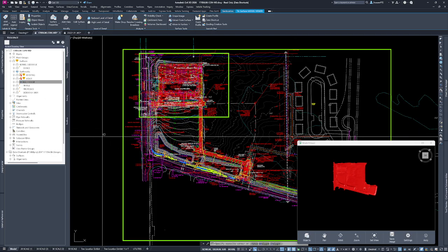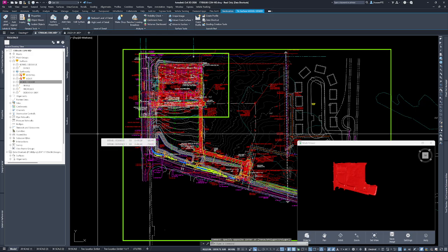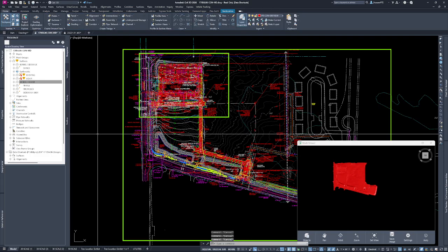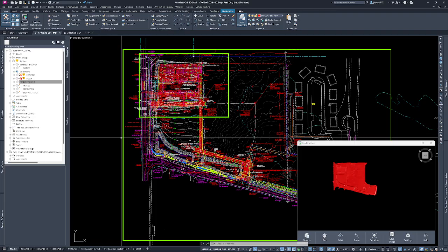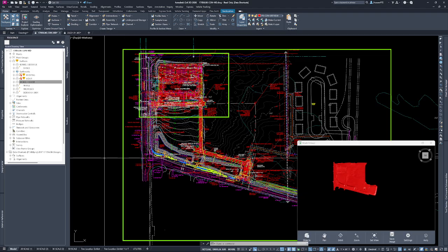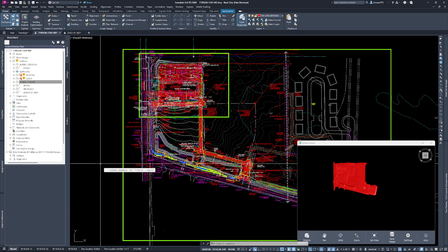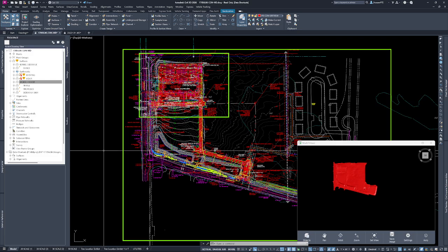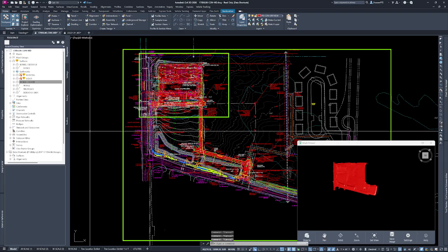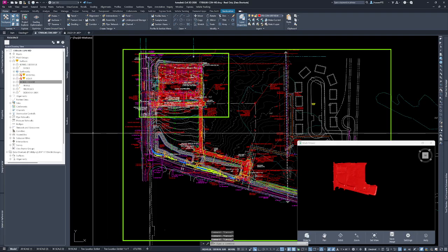The one issue you have to be very careful with is when you're done selecting and adding it to the model viewer, make sure you escape a few times. If you have surfaces that are not being displayed, you need to escape so you don't accidentally move it to a different layer, delete it by accident, or slide it off to the side. It's a common thing that happens quite a bit. You can actually have something selected and not have any visual clues on the screen that you have it selected. So again, hit escape a couple times just to make sure nothing else is selected that you don't want to be.